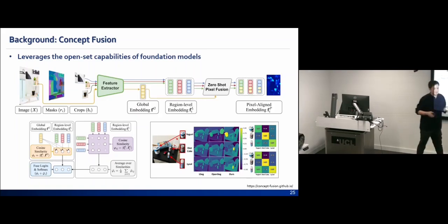It can be considered as object detection, but actually it is an image object localization task. So with Diet Coke, we can also let the model understand where the Diet Coke is. It means that if we can somehow use this CLIP model, we can let the robot understand where the object we want to manipulate is, and then we can execute the grasping or pick and place.